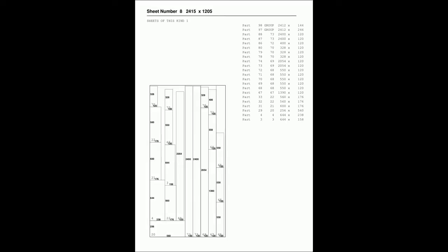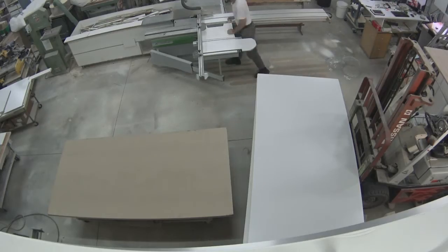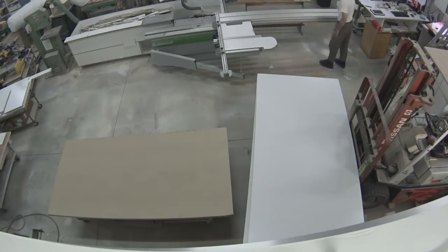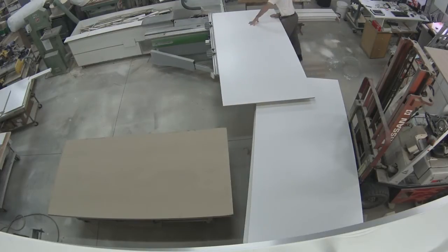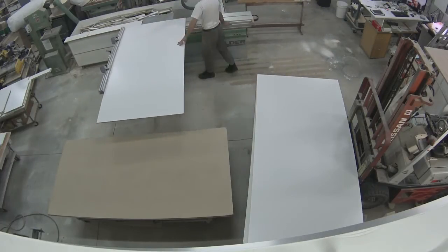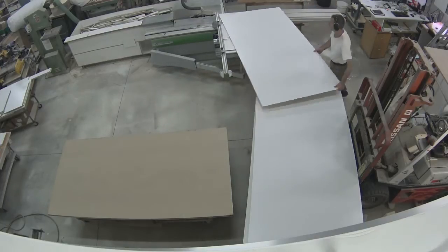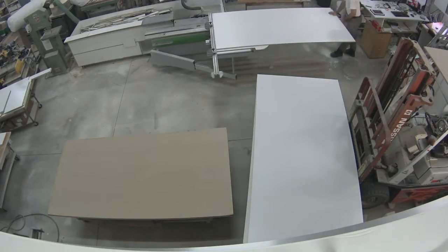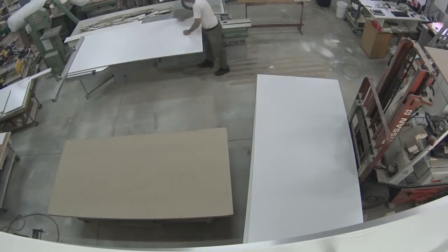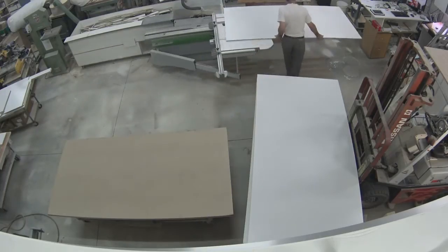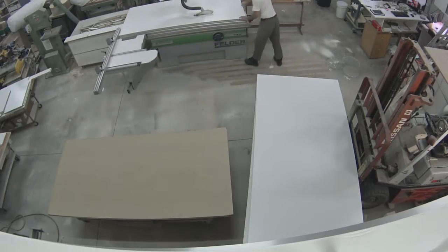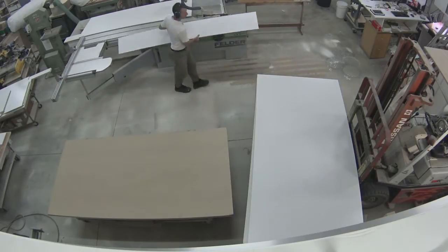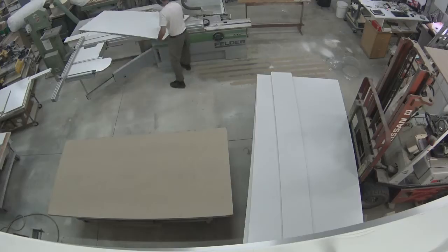Shortly I'll be showing you a video of me doing a cut up. Now here you can see me grabbing the first sheet. Well, it's actually sheet number 4 in that set. None of the sheets are square when you receive it from the manufacturer, and the cuts are very poorly cut. So the first thing you need to do is trim and square up an edge. That's the first rip cut, discarding a piece.